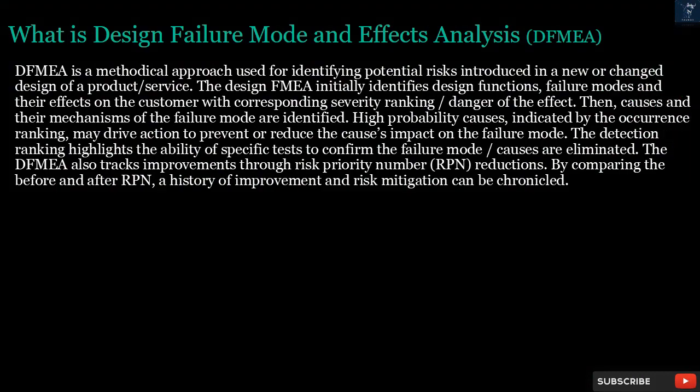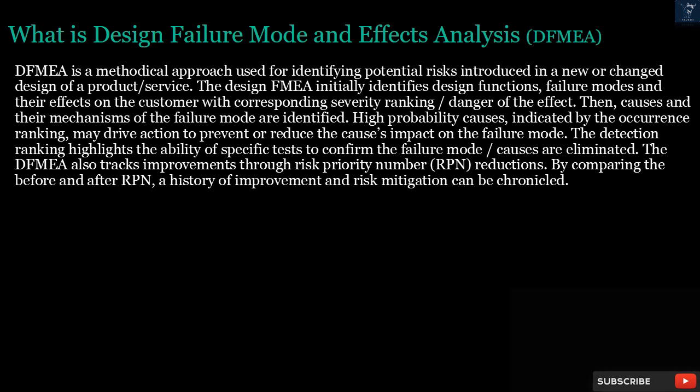What is Design Failure Mode and Effects Analysis, DFMEA? DFMEA is a methodical approach used for identifying potential risks introduced in a new or changed design of a product or service. The Design FMEA initially identifies design functions, failure modes, and their effects on the customer with corresponding severity ranking, the danger of the effect. Then, causes and their mechanisms of the failure mode are identified.